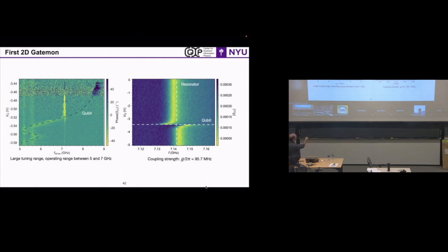Once we know the qubit, we can tune the qubit frequency again over a few gigahertz. The problem that you see is this wiggly line. If it was a gate voltage and a supercurrent, it should be a perfect line, because I'm decreasing my carriers, my frequency should go monotonically. But what happens is that this dielectric stack that I mentioned earlier, and this one is not hBN, is actually aluminum oxide, has this hysteresis behavior. So you're trying to go down, and then it charges up, it stops, and then it goes down again, which is quite annoying.